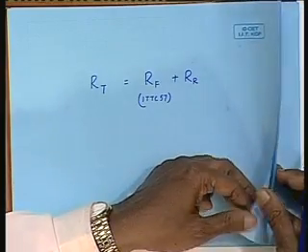Okay. Now, we look at the phenomenon of wave making in ships and see whether we can understand the making of waves and resistance due to it with greater clarity. Whenever a body moves in fluid, there is a pressure force which develops around the body, and that is normal to the body surface.